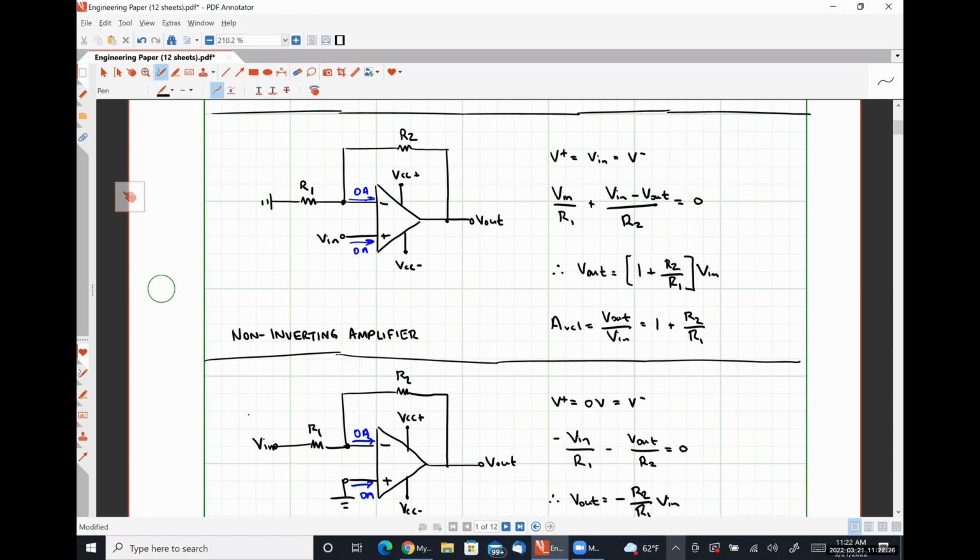Similarly, if we flip this guy around, that would be an example of a non-inverting Schmitt trigger, which we've already done, right? But we cannot arbitrarily change. Positive feedback and negative feedback do very different things. Yeah, so we get very, very different output behaviors. All right, so